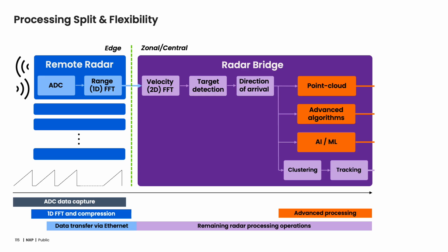You can also look into interference mitigation, multi-frame techniques, and even more advanced approaches like Bayesian learning and lasso, Capon beamforming, all of these things which are high performance but compute intensive. At the edge, they're difficult to implement and still achieve a reasonable radar frame cycle time.